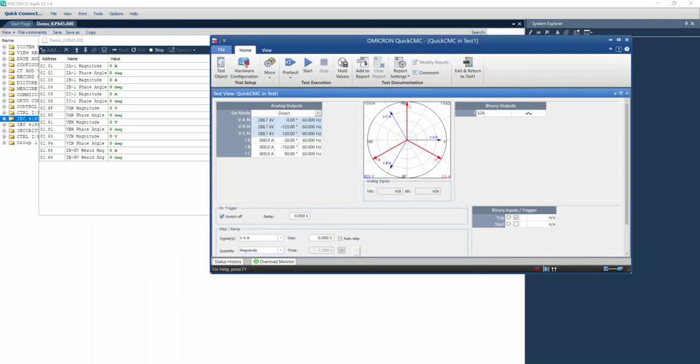Also, in this video, we need to go through the settings of the MiCom to show how it received the sampled values. So before we go to the GOOSE message side, I will take a step back to show how to configure the MiCom to receive the sampled values, by doing some configuration and some settings and sending those to the MiCom relay. In the previous video, we demonstrated how to stream these sampled values.